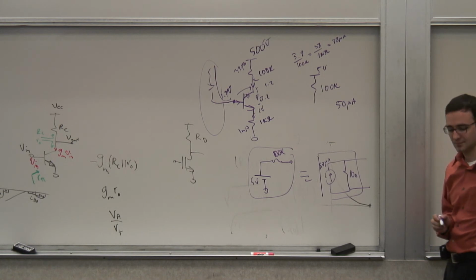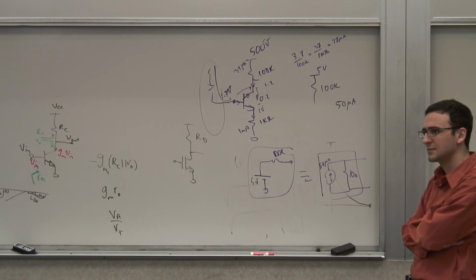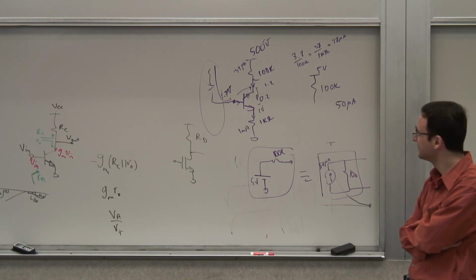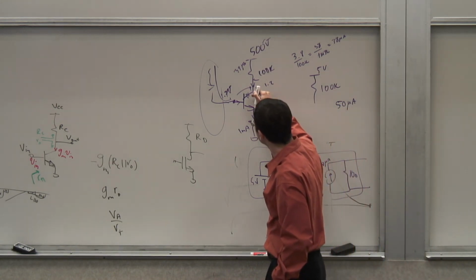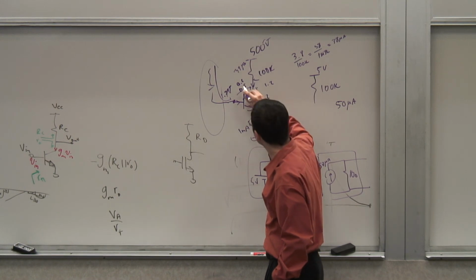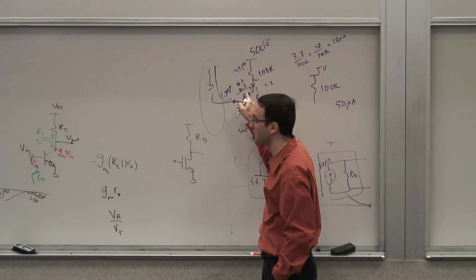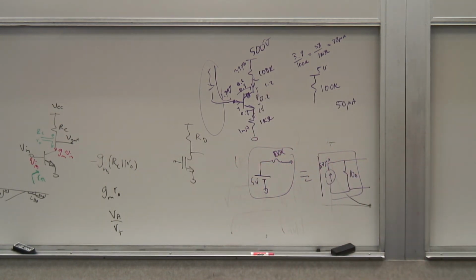So the 0.7 came from the fact that the threshold would be 0.7. I would call it threshold, right? That's not confusing. And the 0.2 comes from the junction. Well, I said, for this junction to start carrying any reasonable current, it has to be at least 0.5 or 0.6 volts forward biased, right? If this is 0.5 or 0.6 and this is 0.7, so it's 0.7 above and then 0.5 below. So it's 0.7 minus 0.5, it's 0.2. That's actually a better way of thinking about it.